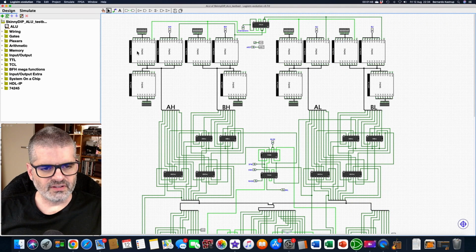These dip switches also have their own driver, and the idea is that by controlling the output enable of these drivers here, which come from a control setting called standalone, if standalone is active, then these drivers here, this, and this, will tri-state. They will go into a high impedance, and there will be nothing on their output. Here, here, here, and here.